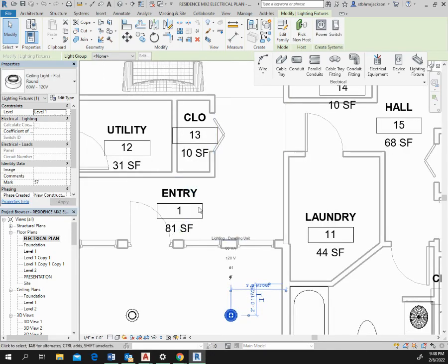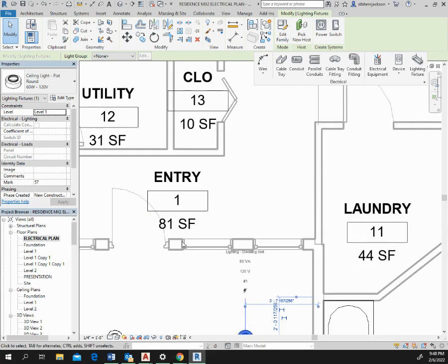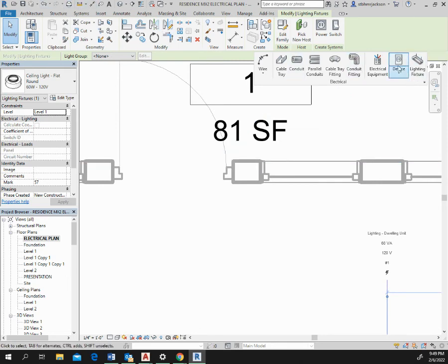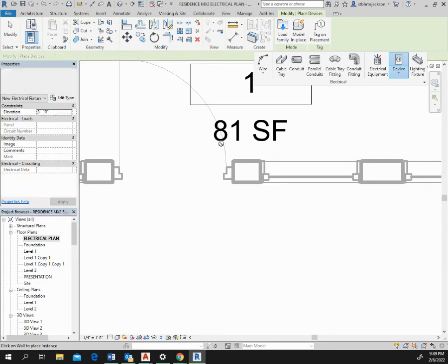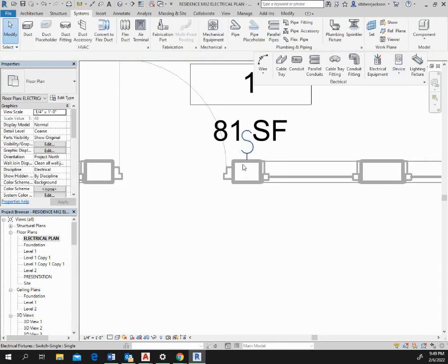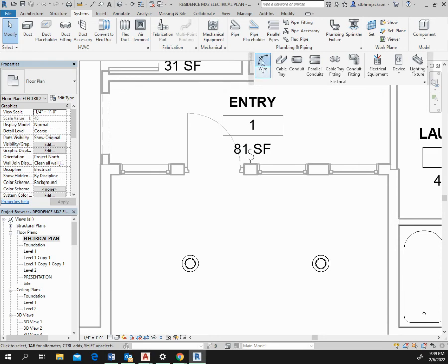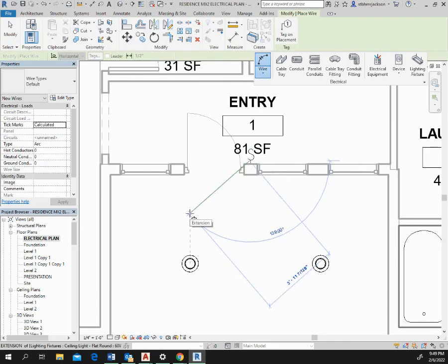All right, so for these, this is a real tight space right here next to this door. I would suggest putting my switches against the wall here because it's not really that far of a walk when you walk in the door to get to the switch. But you might only be able to accomplish getting one switch here. And that's going to be the only one that you'll probably fit in that spot. Realistically, it'll be the only one you can fit in that spot. All right, so when you do two lights, just go in between them, bend it.